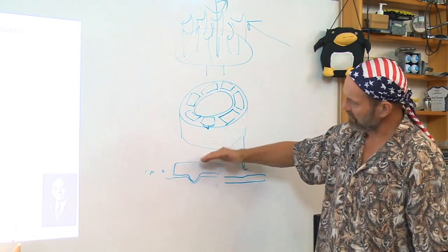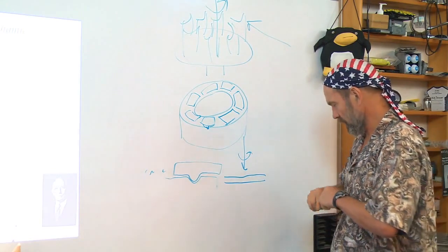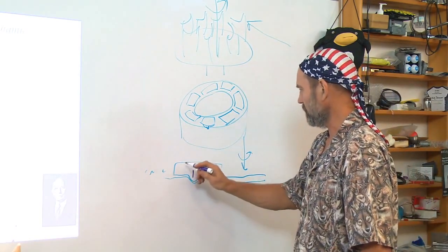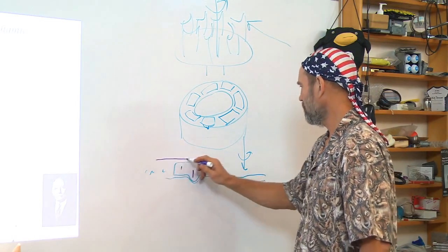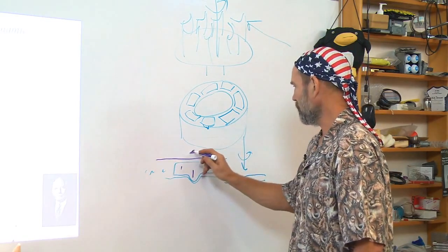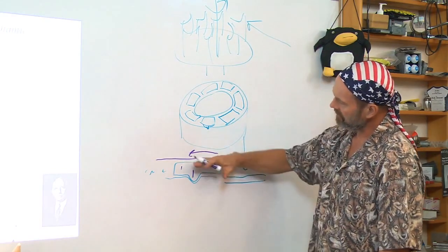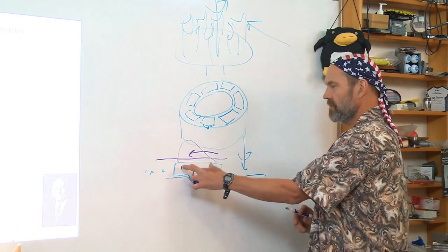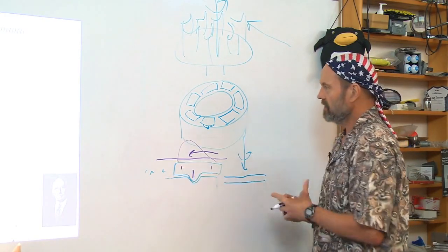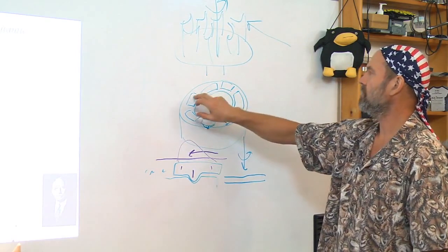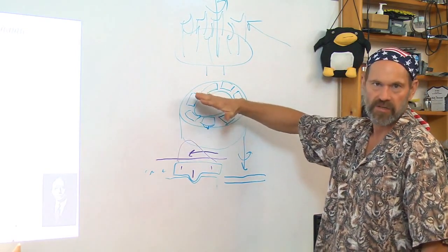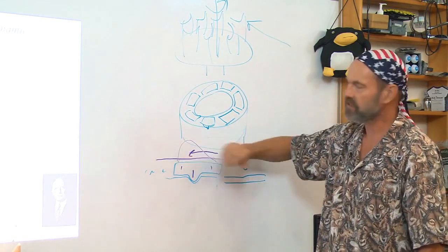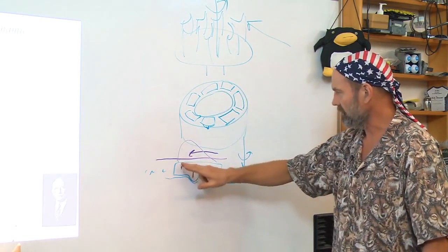If this tilts a little bit as the upper surface is moving, because you have a little bit of an eccentricity here, I'll build up this hydrodynamic wedge and pressure profile over this tilting pad. And when I have a whole bunch of these tilting pads, it's now very easy to get them all. You never have to worry about them being aligned in tilt because they will self-adjust. They just have to have a common plane